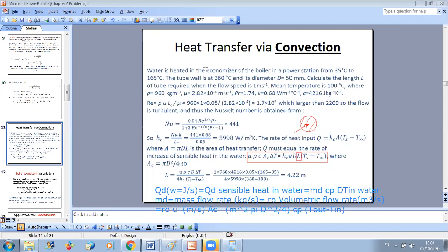Now, which one to select? Based on research and experience, we can know that, for example, this one works better, or here you have a smooth surface. In case you have a certain roughness, the empirical relation for the Nusselt number will be different. So even though it might be new for you, even for the same type of flow, we have several works done.